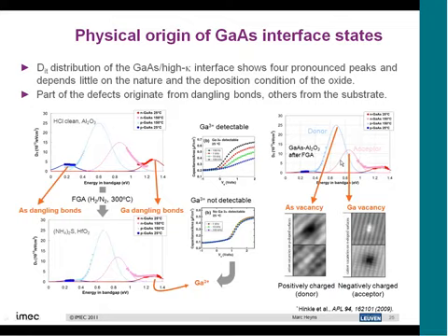The reason why you make them is that they come from the stress that you generate in the material by growing the oxide, which makes gallium and arsenic diffuse into the oxide, leaving arsenic vacancies or gallium vacancies, making arsenic bonds that are electrically very active defects, which are then present in the bulk of the material. So not at the interface, they are really in the bulk, very close to the interface, and that's why they give this very typical shape and this very typical Fermi level pinning.